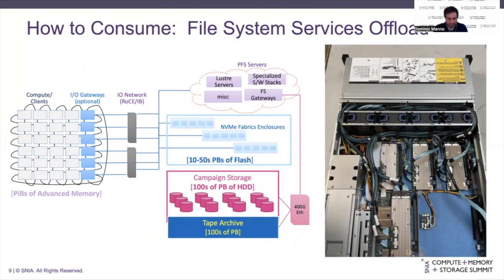Okay, so here on the right depicts the accelerated box of flash. It looks like a standard server with 24 NVMe drive bays in the front. But there's actually no CPU in this particular version of the ABOF. We have a variety of versions of the ABOF. Some of them have lightweight CPUs like ARM. Some of them have heavier weight like AMD. But in this case, we were exploring using an NVIDIA DPU, the BlueField architecture, to test its capabilities as being the DPU of choice for the enclosure. We also have FPGA PCIe slots for FPGAs to be inserted. And then there's also the capability to install U.2 FPGA devices in the NVMe drive bays.